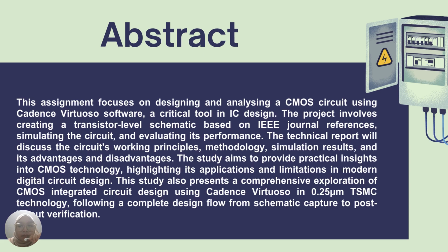Our project aims to design and analyze a CMOS circuit using Cadence Virtuoso, a leading tool in IC design. Three key steps include design, which is creating a transistor level schematic based on an IEEE journal reference. Second is simulation, which is evaluating circuit performance through rigorous testing.